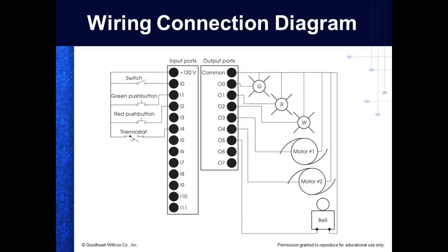Then they dropped down to 24 volts. So 24 volts is a very popular control voltage. But it's a range. It's usually like 20 to 30, which is what your input modules actually accept. So when I see 120 volts, that's what our control systems are, so I say 120 volts. But it could be DC. But if it's DC, then we're going to have to specify whether it's what? Sinking or sourcing.